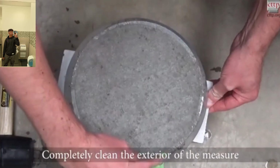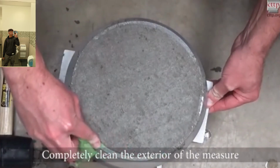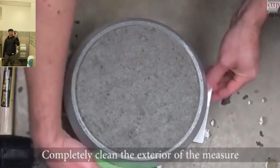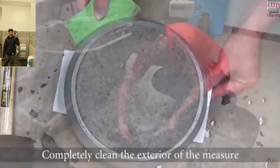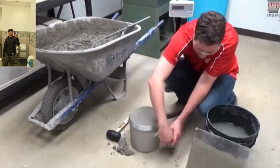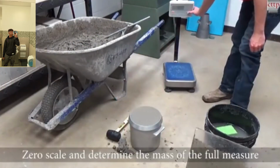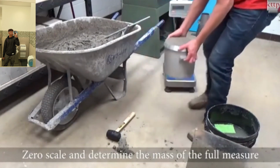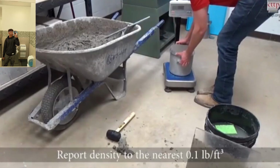Completely clean the exterior of the measure. Zero the scale and determine the mass of the full measure. Lastly, report the density to the nearest 0.1 pounds per cubic foot.